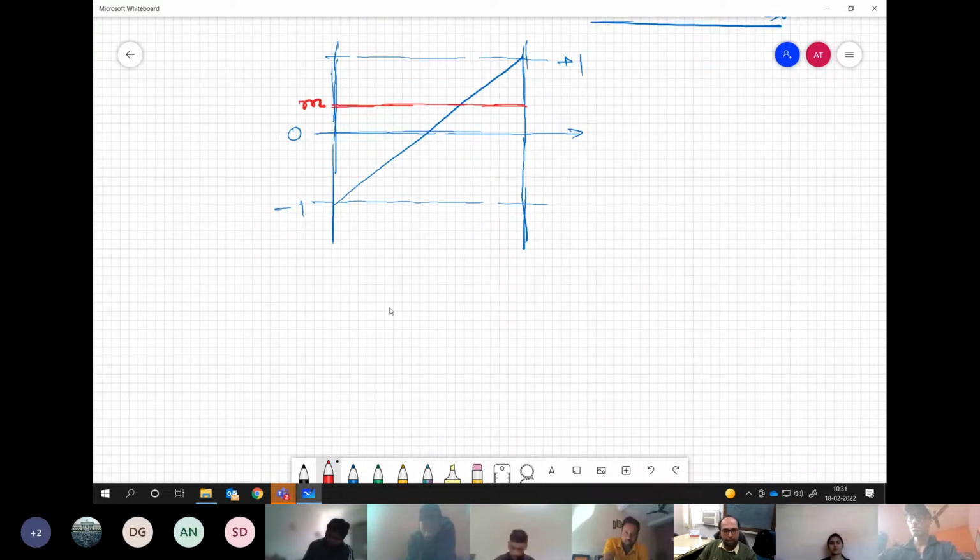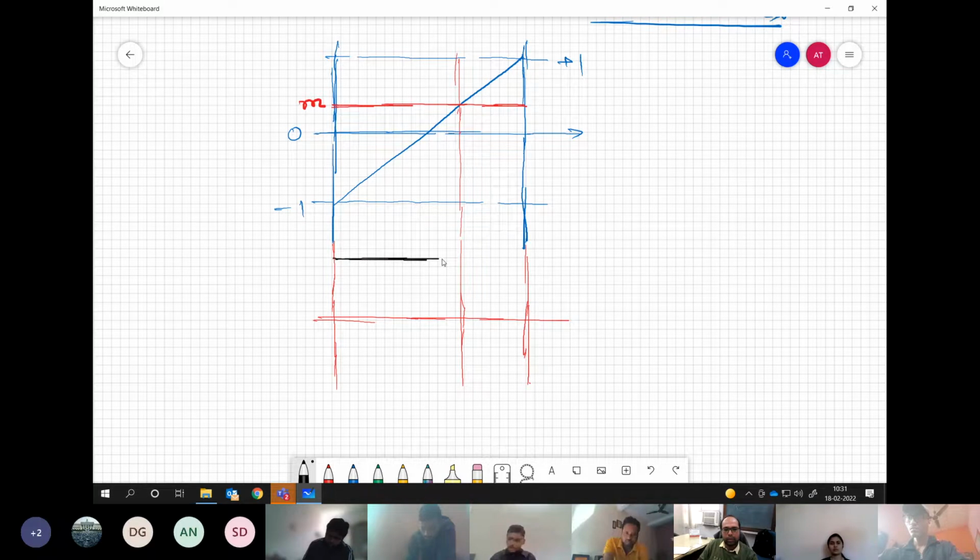Now what will happen when you apply this kind of reference and carrier and then operate the switch? You will generate a voltage which will be of this nature. So plus VRO up to this point, because whenever m is greater than the carrier, we have VRO equal to plus VDC by 2.